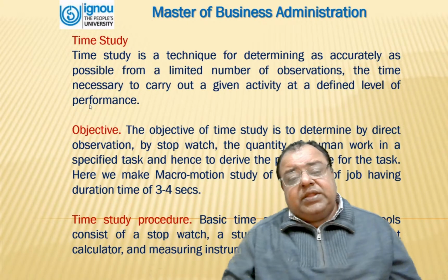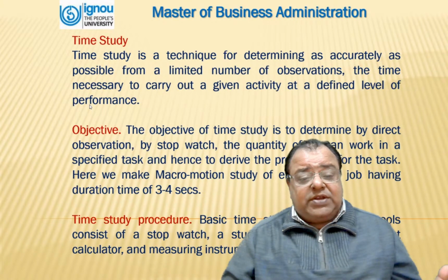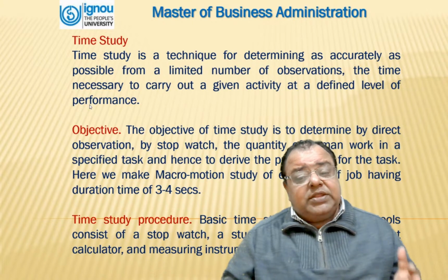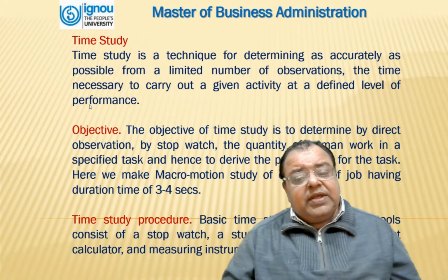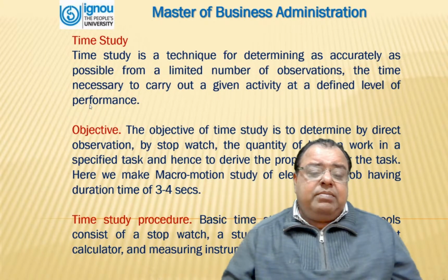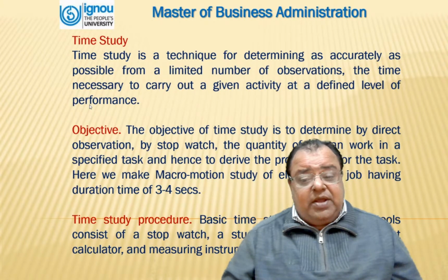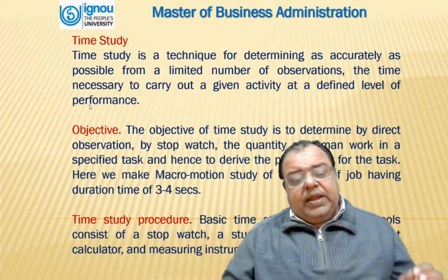The objective of time study is to determine by direct observation, by stopwatch, the quantity of human work in a specified task and hence to derive the proper time for the task. Here we can make a macro motion study of elements of a job having duration time of 3 to 4 seconds.